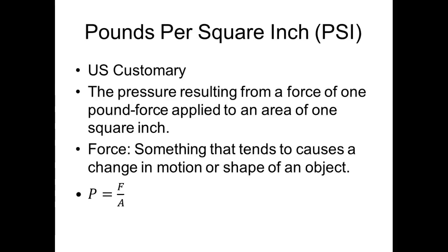Well, we can rearrange that and say, okay, pressure would be equal to force divided by area. So if I can measure a force mechanically, and then I can divide that by an area, this is the way we have to measure pressure, right? So we're not measuring pressure directly, we're measuring pressure indirectly. By doing what? Measuring the force, and then we have to know the area that force is being applied to.